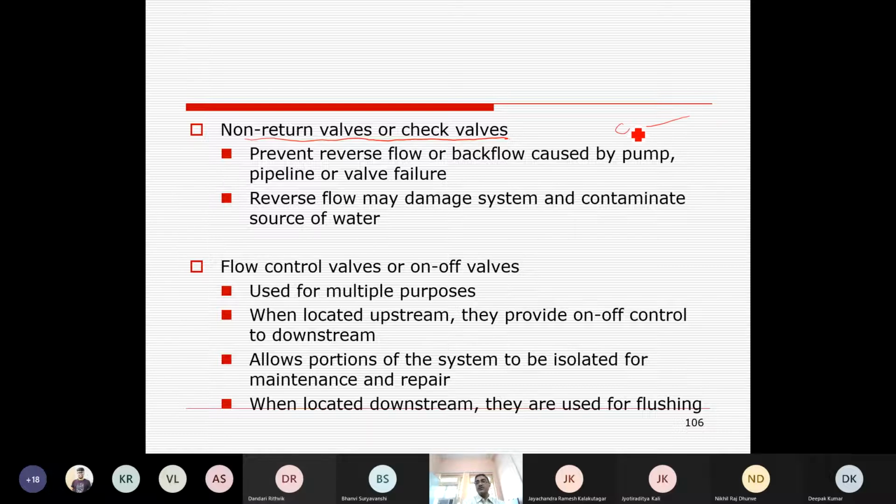Once the pump is closed, water will flow towards the gravity, means if the supply side is at the lower level, it will come back or go downside with a fast speed that may damage the pipeline. That is called water hammer condition. So the non-return valve is basically placed in the main and sub-main lines to reduce the chances of damaging pipelines.